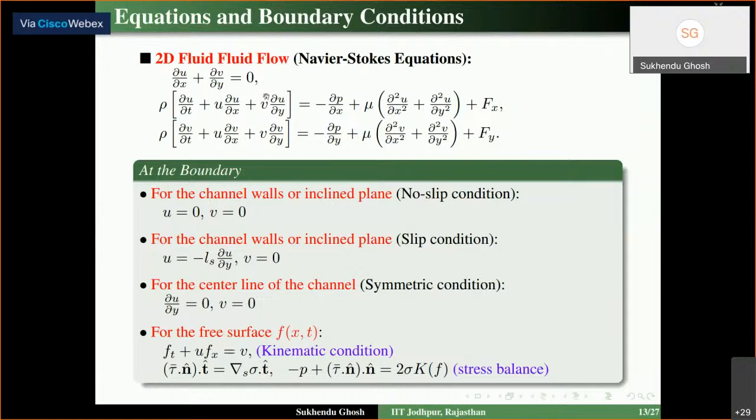That is fine. Now, if you look at the second equation, the first term, you can see that we have mentioned all the variables in the equilibrium state are time independent as well as not much varying with respect to space. So del u by del t will be 0 because u is only dependent on y. Similarly, del u by del x is also 0. So the first two terms will not give you any contribution in the case of the equilibrium solution.